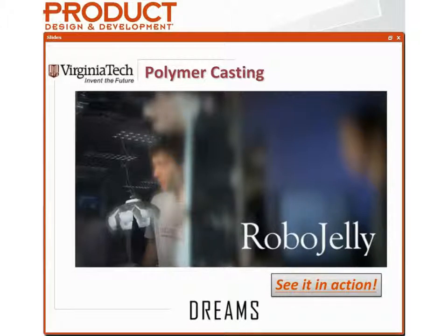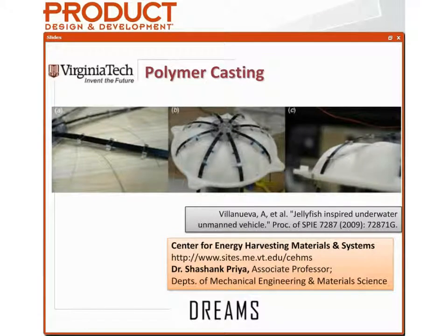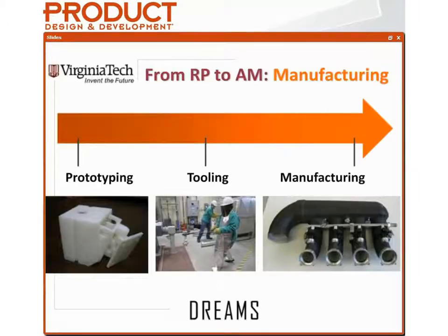So you might ask yourself, how in the heck do they make that? So I'll invite you to come back to our presentation. The way in which they made that, again, that was a silicone jellyfish with embedded shape memory actuation. And the way in which that was done actually was through 3D printing. So using an FDM printer, we printed a shell into which we can then cast this silicone material. So they were able to digitally design and then fabricate that mold using FDM. They then lay in their shape memory alloy and the spring steel there, then close that mold and cast the device.